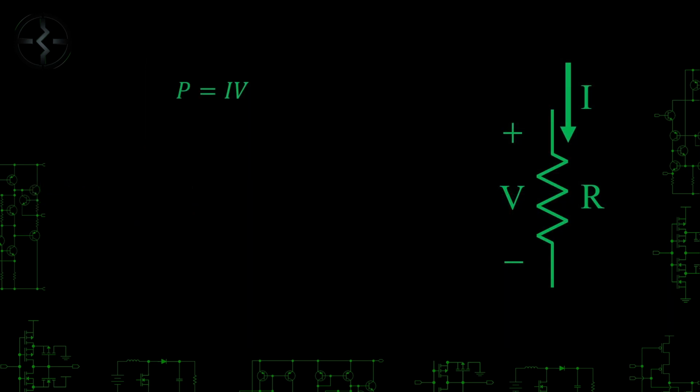The last thing we want to know is how much power this resistor needs to dissipate. This is a critical step that's often ignored. Make sure to get a resistor that can handle the power, or you might end up making a fire starter instead of a light.